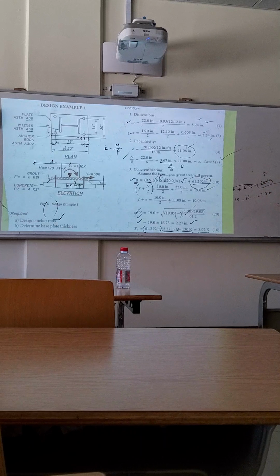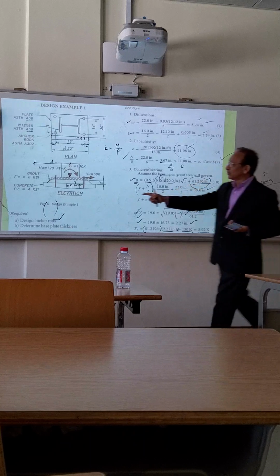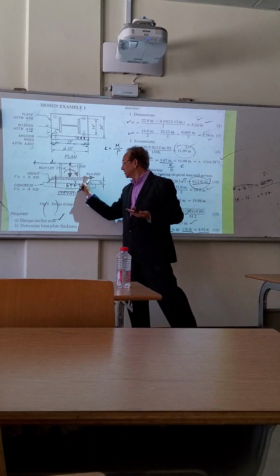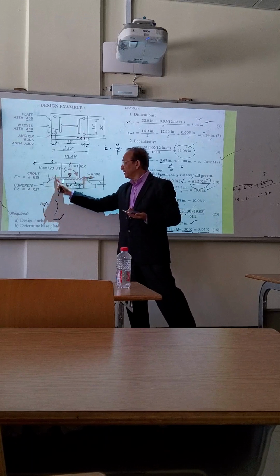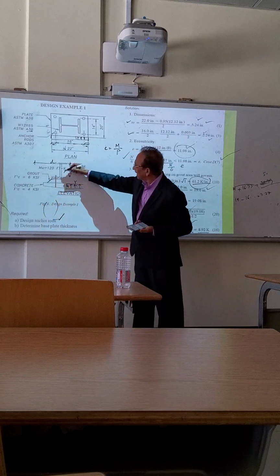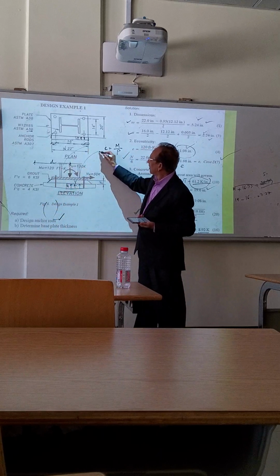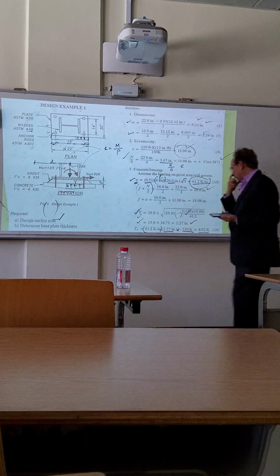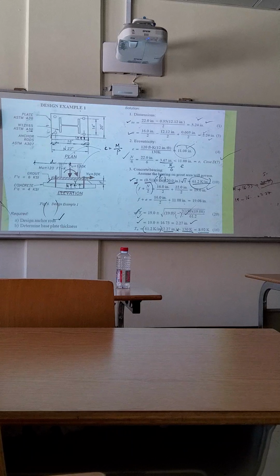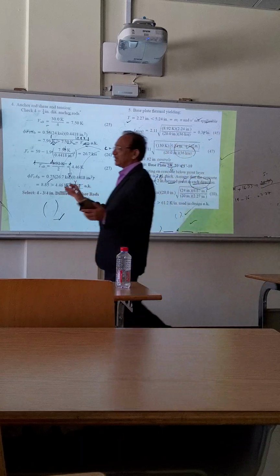Okay. So we get the tensile force, and that tensile force will be taken not by concrete, because concrete cannot take any tensile force. So that tensile force will go to the bolts on this side. These bolts will not take any because they will be in compression. Only these bolts, because your bending will take place like this. So this will be compression, and this side will be tension. So we have now the tensile force. Now your job is to start the design process.